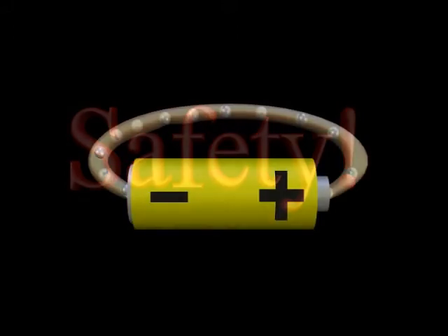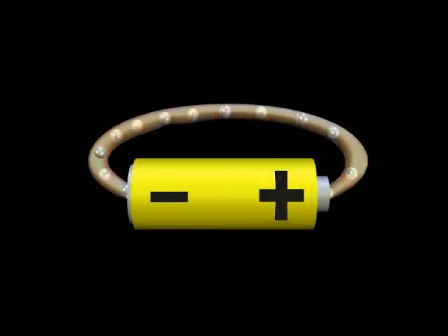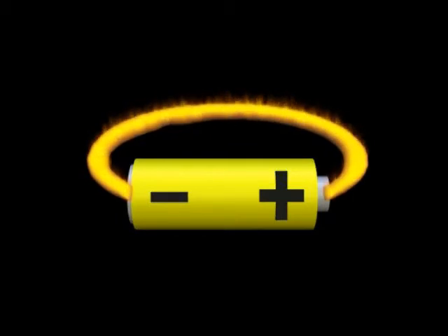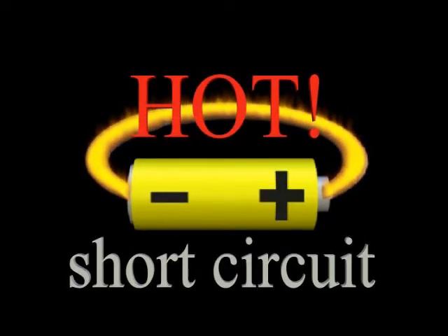Here is a safety caution. Never connect a short metal wire between the terminals of a battery. This is a short circuit. The wire will get hot, you might burn yourself, and the battery will quickly lose its energy.